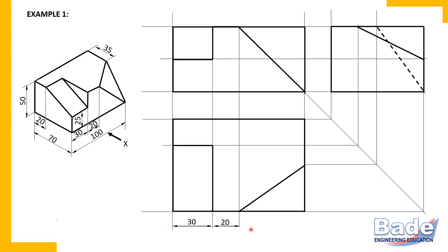This is chain dimensioning. Dimensions in series. Remember this. Dimension line is a thin line. Arrows are elongated and filled. Dimensions must be written above the dimension line, but these numbers must not touch the dimension line. Chain dimensioning. Dimensions in series must be along single line, that is collinear.